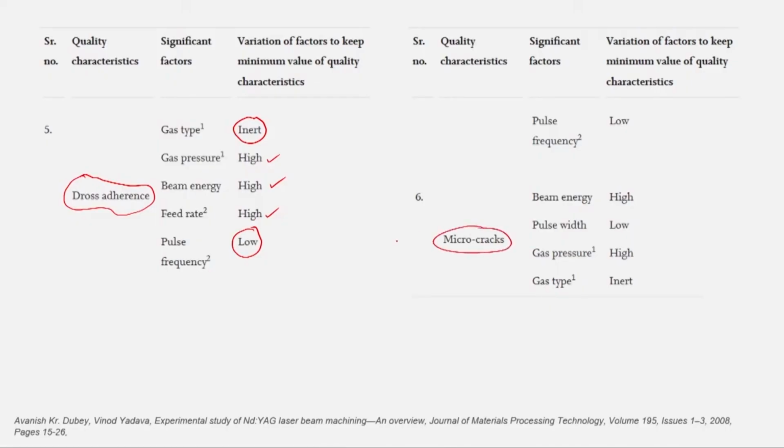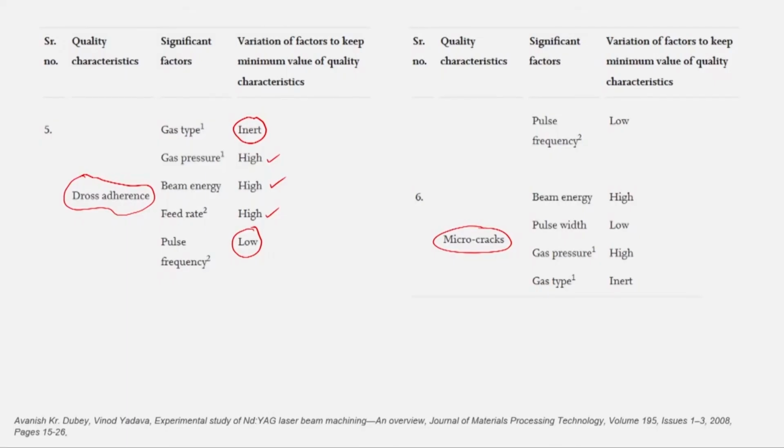Now, cracks or micro cracks, as I mentioned, matter when these laser based components are used in high fatigue applications where the endurance strength has to be high. So, the cracks are very dangerous during such applications. The laser processed parts are to be examined for micro cracks, but the micro cracks can be minimized, they can be controlled at the time of their manufacturing.